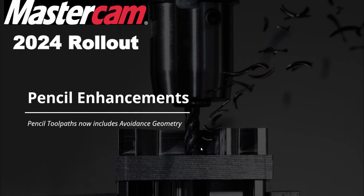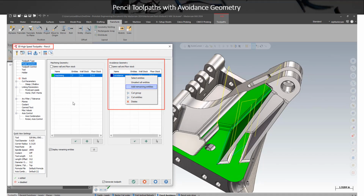I really like the pencil toolpath. We saw a lot of enhancements to it when it was new. Haven't seen much enhancements to it for a while. It's nice to see an enhancement to it again. And what they've done is pencil has never supported avoidance geometry. Now it does. So I've figured out workarounds because I've been using it and love it for years. So I figured out workarounds, and now you could still use the workarounds. So if you have stuff that works, that should still work. But now you have the additional choice of using avoidance geometry with your pencil.